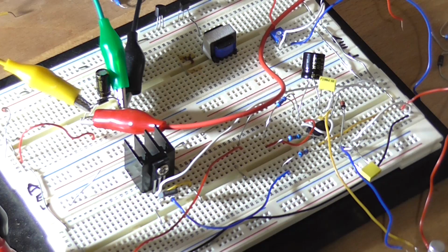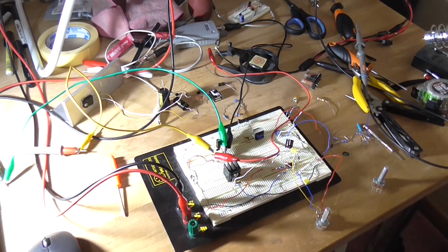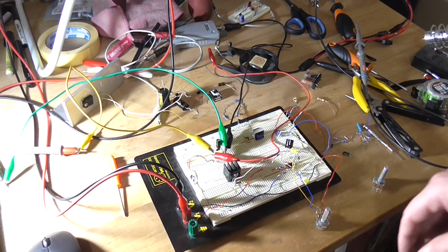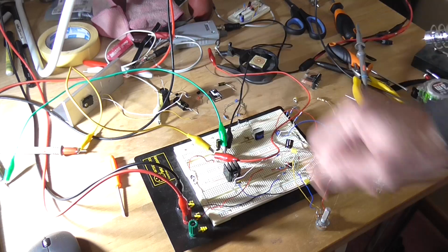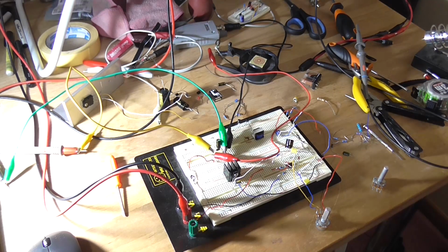So let's look at this circuit now on the breadboard and take some measurements and see how it operates. So there's the new circuit built there. I've got the power supply turned on, but the load isn't connected at this stage. So I'll just turn the supply's load on. Nothing happened. I'm also using just a 100 microfarad capacitor across the motor instead of 1000. And for this particular circuit, it seems to work okay.